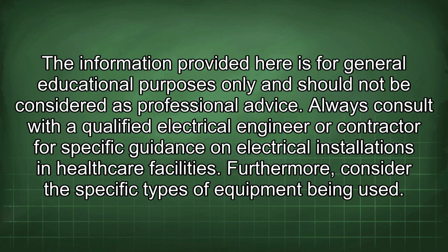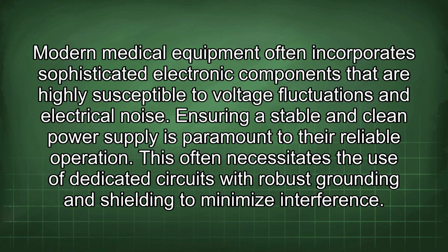Always consult with a qualified electrical engineer or contractor for specific guidance on electrical installations in healthcare facilities. Furthermore, consider the specific types of equipment being used. Modern medical equipment often incorporates sophisticated electronic components that are highly susceptible to voltage fluctuations and electrical noise. Ensuring a stable and clean power supply is paramount to their reliable operation. This often necessitates the use of dedicated circuits with robust grounding and shielding to minimize interference.